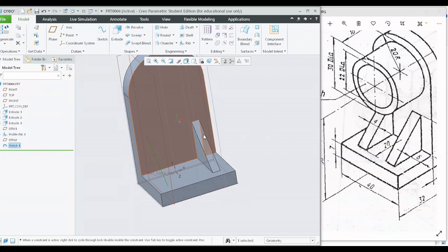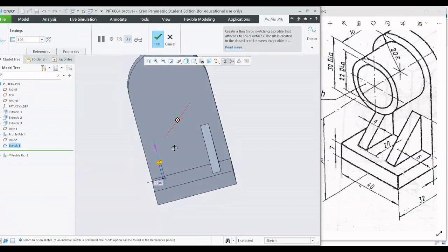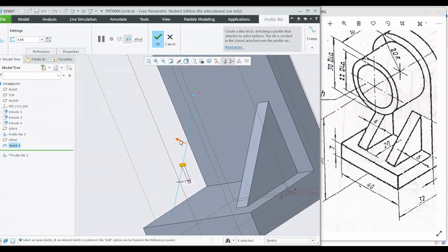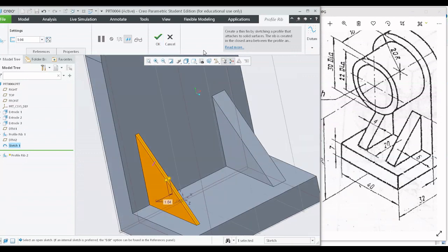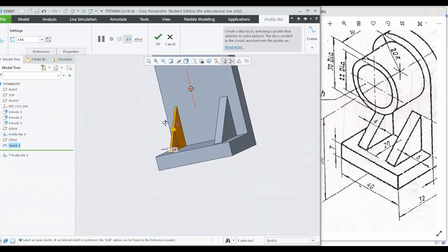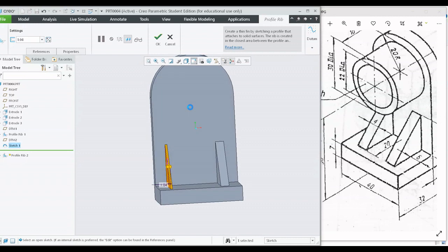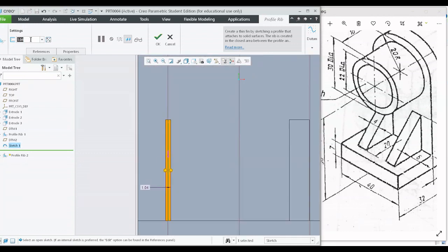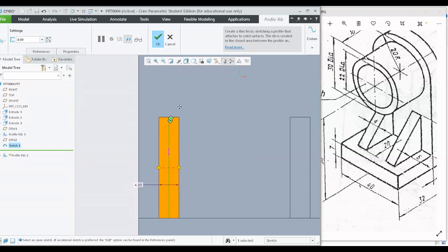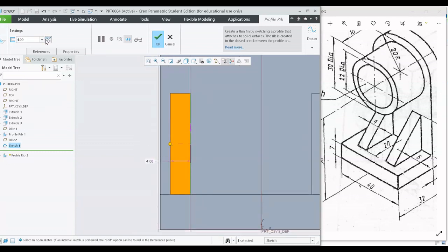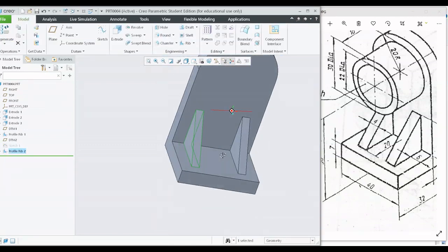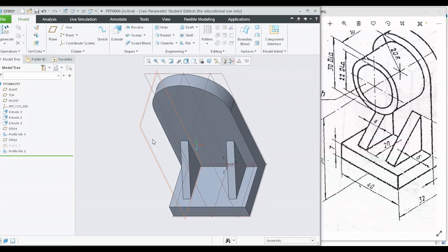Sketch is highlighted and let me click on the rib. So the direction of the rib is on the other side. I have changed it to the other side, that is inside, nearer to the geometry. And let me align the view to front view so that I can see the location of the rib. The thickness has to be 4 units and the rib need not be symmetric. It has to be on the other side of the plane. So I have created the rib using the new sketch. So you can see that in this particular geometry, we have created 2 additional sketch planes.